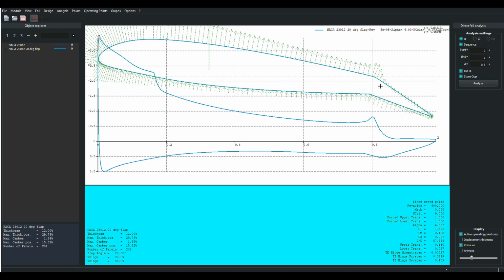So essentially we have an airfoil strapped down to the back end of our airfoil, and when we deflect it, it generates a lot of lift back here at its leading edge, and that's what gives us the nose down pitching moment. We're adding lift back here. We've got a force pulling up on the back end of the airfoil, and that pushes the front end down, which is what we want. We give down elevator, we want that nose to go down.